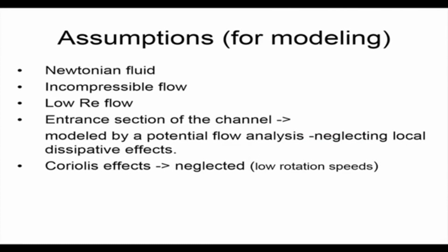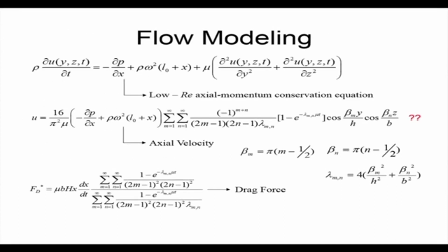Some assumptions are taken for the results that are presented here: it is a Newtonian fluid, incompressible, low Reynolds number flow, entrance effects are neglected and Coriolis effects are neglected. Coriolis effects are actually not negligible at high rotational speeds. So these experiments are for low rotational speeds.